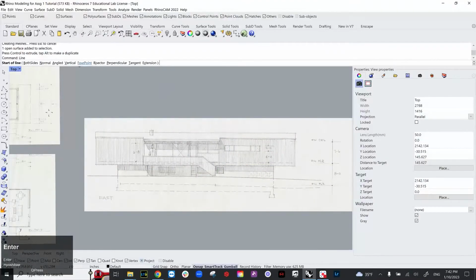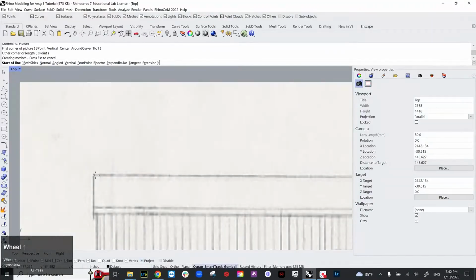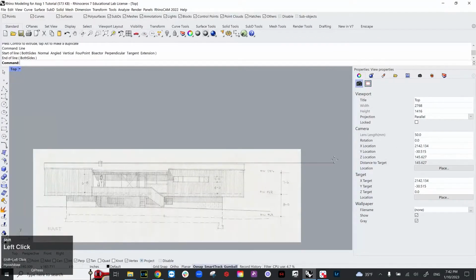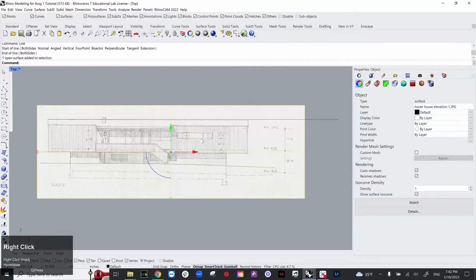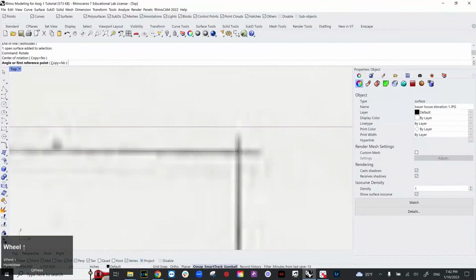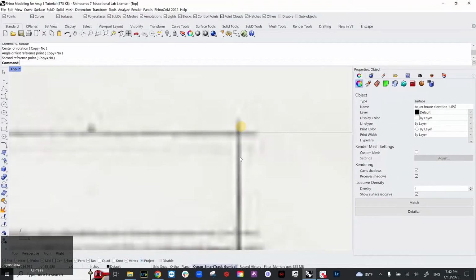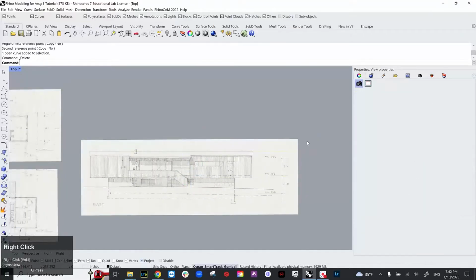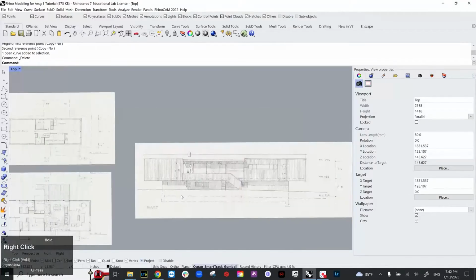I'm going to check this drawing. I probably have to rotate this. So same process as the floor plan. You just have to rotate your JPEG image first to make sure all the lines are straight, and then scale them.